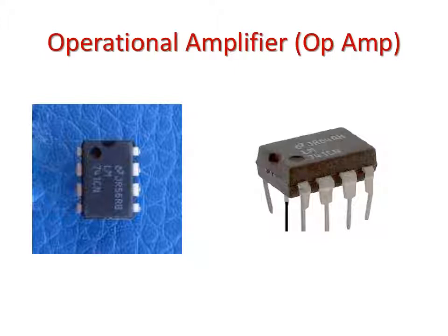The signal out, and where that comes from, you can look at the graphs of how that's developed. Again, they're all going to function under the same gain equations that we used previously, but some of them have other different properties, so low current op amps, high current op amps, etc., that make those op amps unique and sometimes more expensive and more worthwhile for different applications. So again, what I'm saying with this is when you're using op amps for filtering, make sure you match the right op amp to the right filter job.